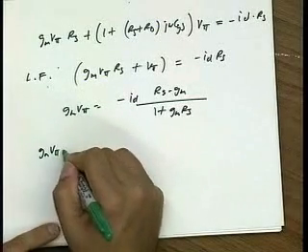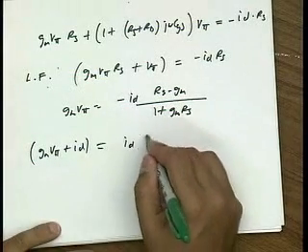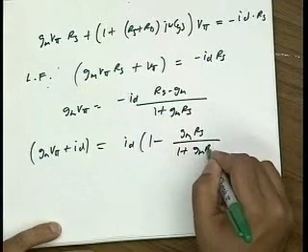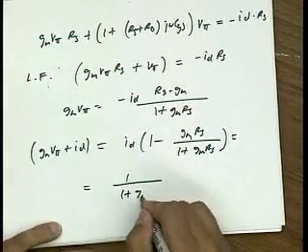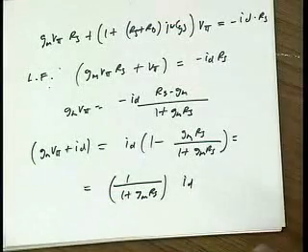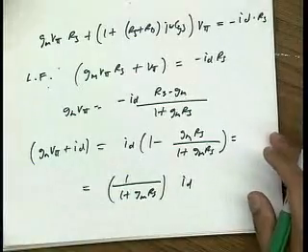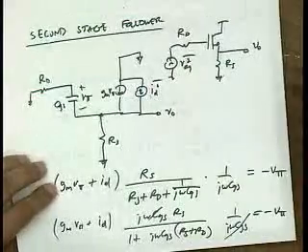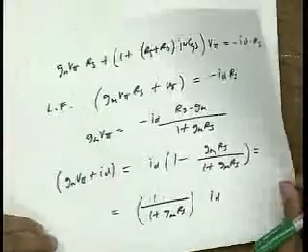because it's exactly the same problem. So now I sum currents, and you can see that Id gets canceled out partially. And we get this suppression factor. So the lesson is that, again, if you'd done a lot of homework problems, you wouldn't have to do all these calculations. You would just say, oh, I know that the sum of this current and this current is the drain current divided by 1 plus gm RS. Right? I'm done. I don't need to redo that calculation again.